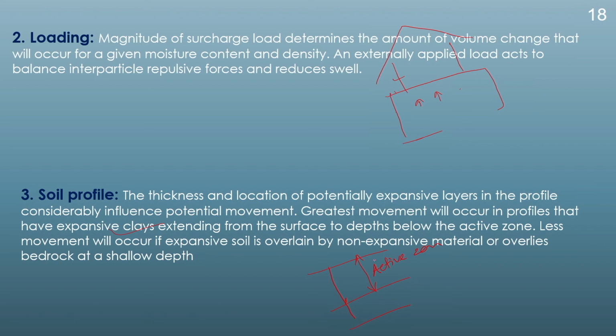At the same time, if this is an expansive soil, and if a non-expansive soil is present over this soil, in this case the swelling of this expansive soil will be less, since the weight of this non-expansive soil can counterbalance some of the swelling pressure, and therefore the swelling of the soil will decrease.